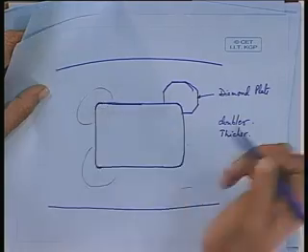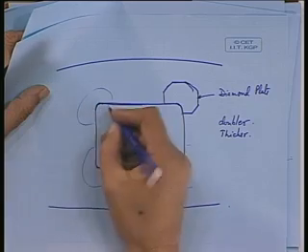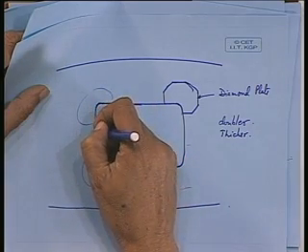In fact, one thing can be added to this part here. When you are taking out material from here, or let us come to this joint here, how do we take it out? We burn it out basically. So, with oxyacetylene gas you try to heat it, and then high pressure oxygen you blow it off, and therefore you get a neat cut here.